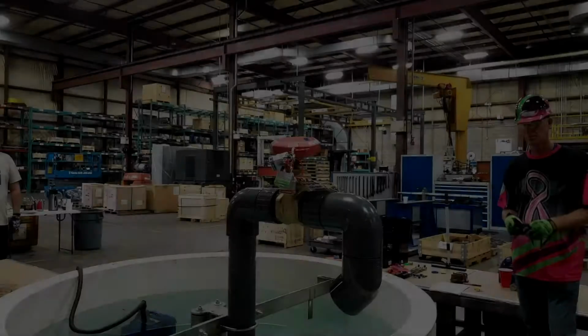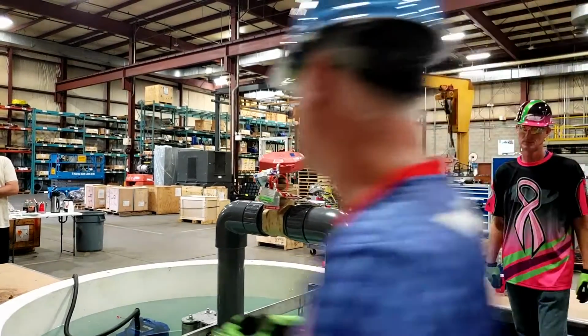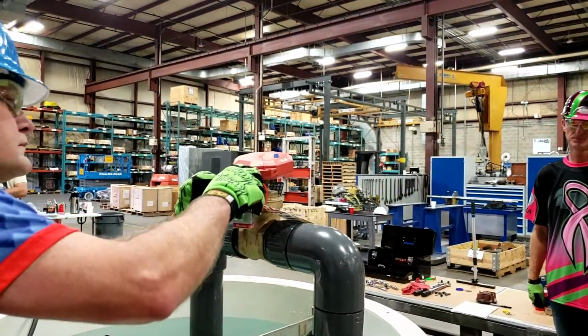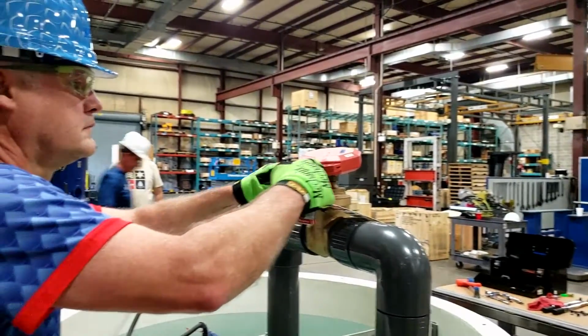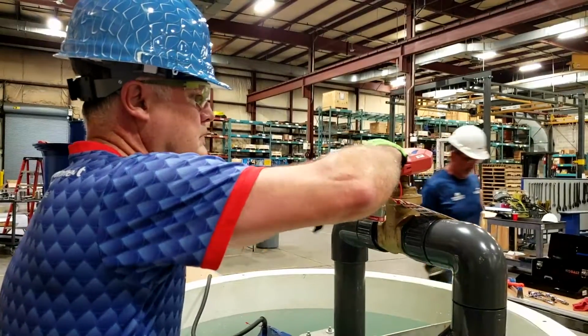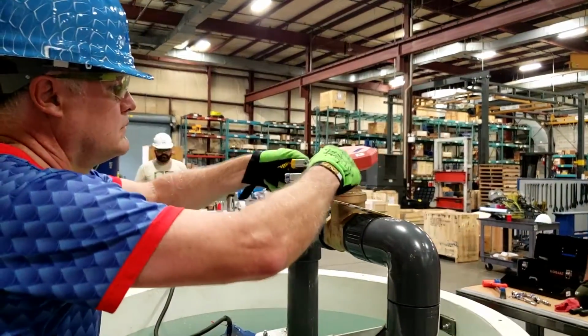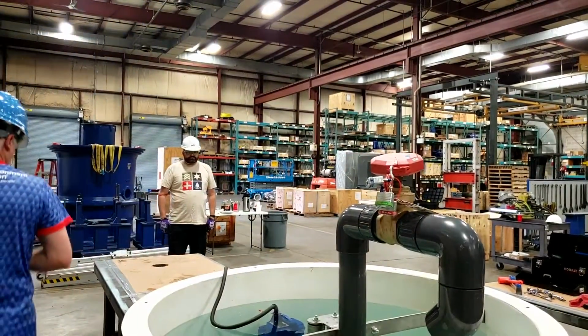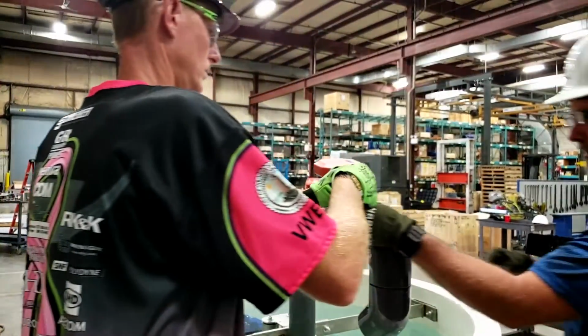KSB Pump Maintenance Event Task 14. Returning the 3-inch gate valve back to service. Each team member will remove their locks, gang hasps, and lockout tags, and the valve bonnet will also be removed. You'll fully open the 3-inch gate valve. You'll communicate out loud that the gate valve is open.